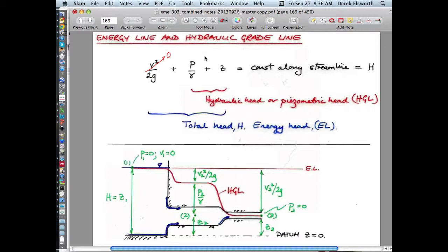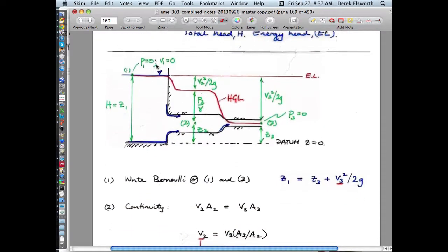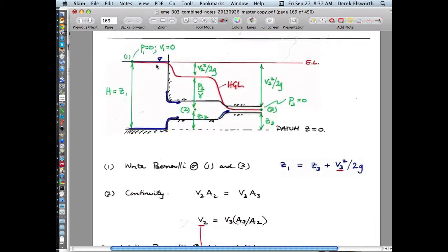So everything that you do in petroleum engineering in terms of Darcy's law, or in environmental systems engineering, or mining engineering, for that matter, or energy engineering that uses Darcy's law, it uses Bernoulli, it uses hydraulic head, and it throws away this term because the velocities are trivial, that they just don't make any difference. The velocities are small, so there's no inertia. So you're not accelerating fluids greatly. The viscous losses in the system are much larger than the accelerations you have in the system.